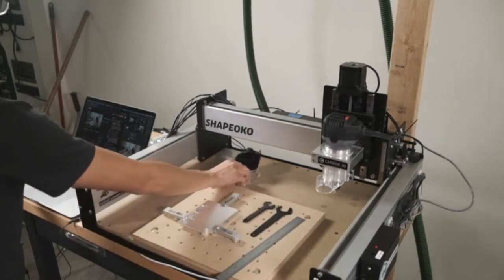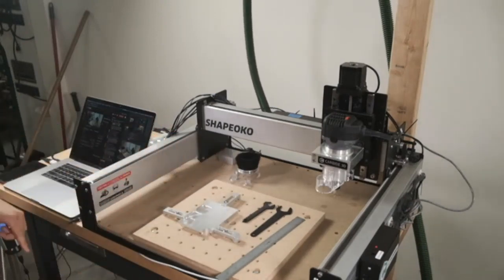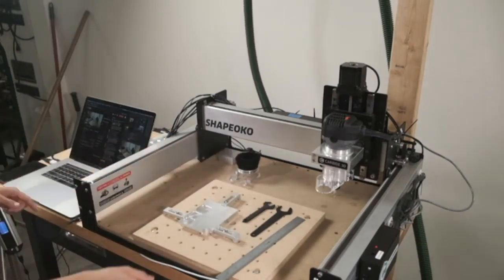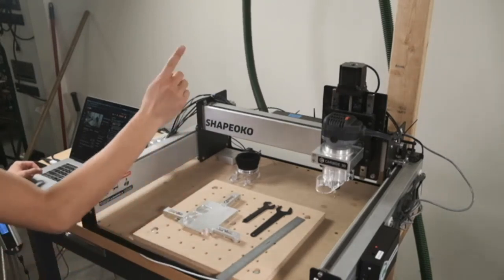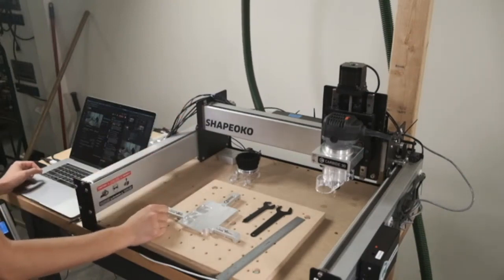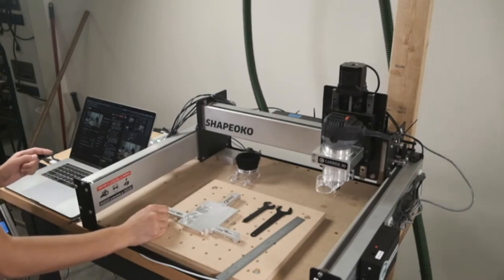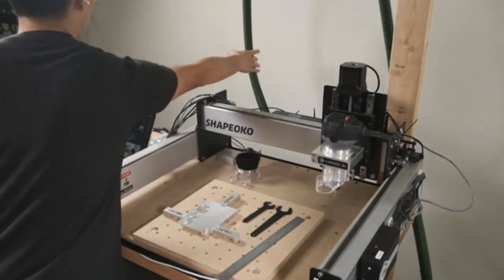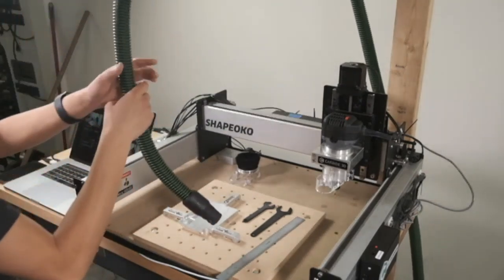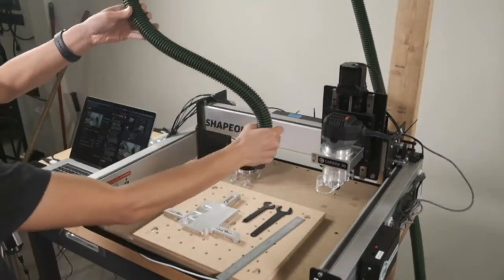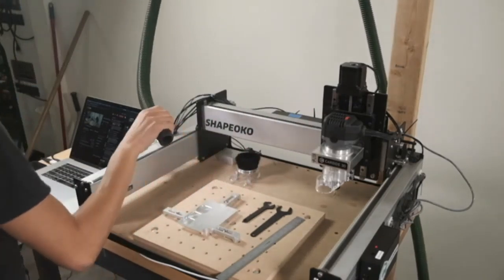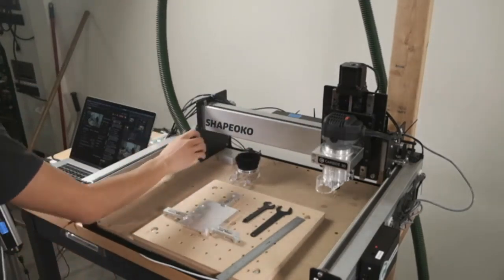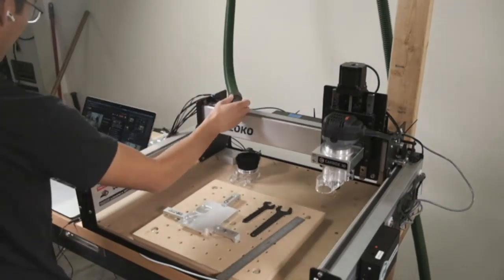And then, yeah, that is my dust collection setup. I have a different dust separator at home, but this is the same basic setup. I still use the gate hinge, and it works out pretty well. The only thing you have to keep in mind is the radius of that dust arm that swings out: you have to make sure you have enough slack for the hose to reach every corner of your CNC. A nice flexible hose would be even better, but this is what I got.